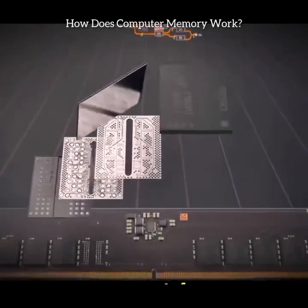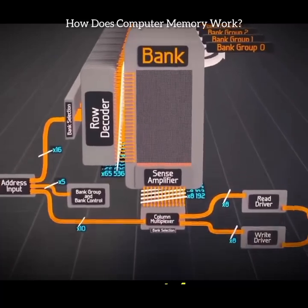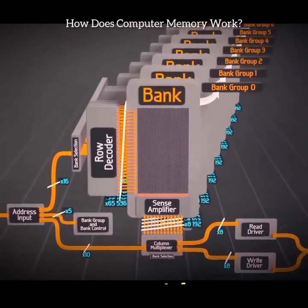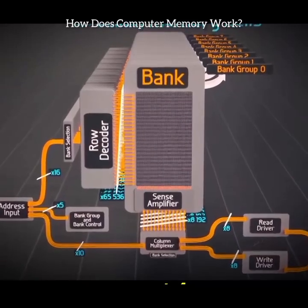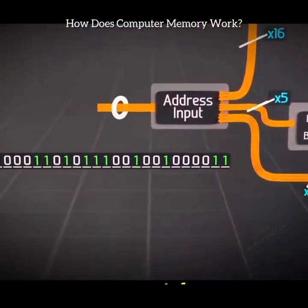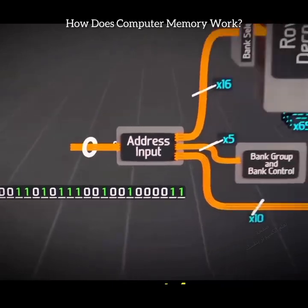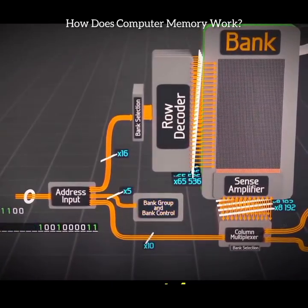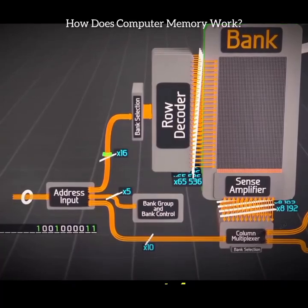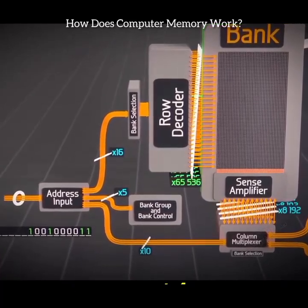Instead of looking at this die, we're going to transition to a functional diagram, and then reorganize the banks and bank groups. In order to access 17 billion memory cells, we need a 31-bit address. 3 bits are used to select the appropriate bank group, then 2 bits to select the bank. Next, 16 bits of the address are used to determine the exact row out of 65,000.